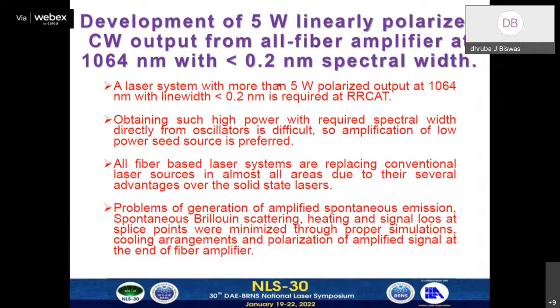Now this amplifier can be based on conventional solid state amplifier or fiber based amplifier. Now we are preferring this fiber based amplifier because fiber amplifiers have many advantages over conventional solid state counterparts. Now, the main problems associated with the fiber amplifier are generation of amplified spontaneous emission, that is ASE, SBS, heating, and signal loss at the splice point. So before the actual design, we have taken proper simulations to minimize these effects. Next slide, please.